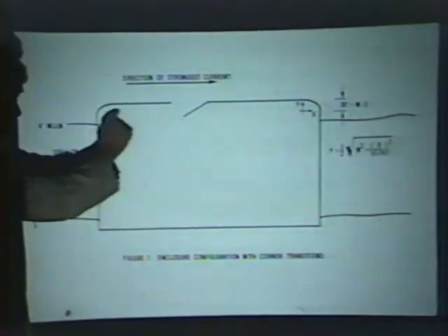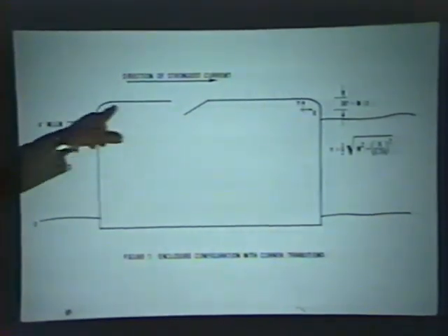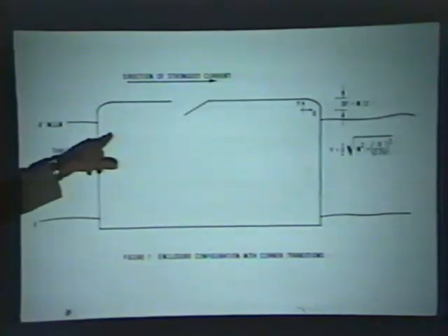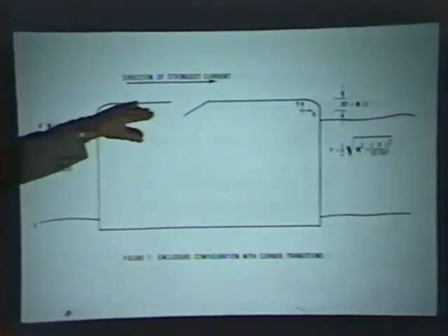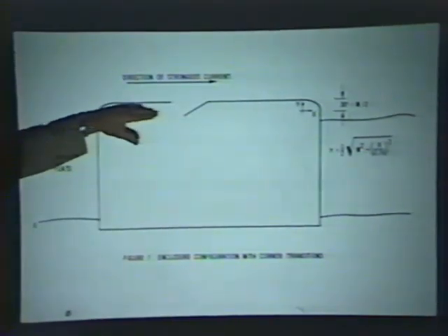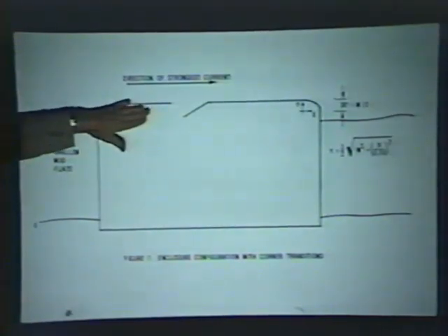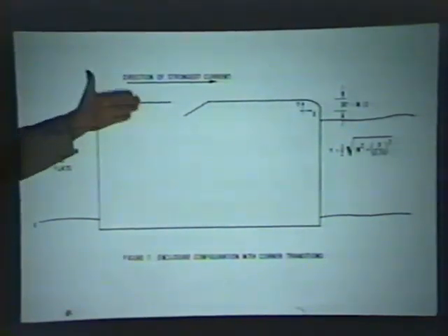And in the design of these, at least these outer breakwaters, it's important that you calculate the waves that are liable to impinge on it, and the wave height and the tide together shouldn't overtop the wall with solid water. The top elevation of the wall needs to be high enough so that only spray goes over the top. The boats inside can stand spray, that doesn't bother them. But if you have significant volumes of water coming over the top, then you can have damage inside.